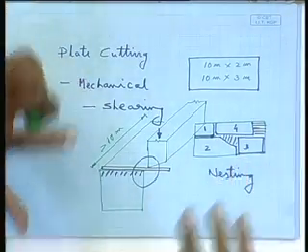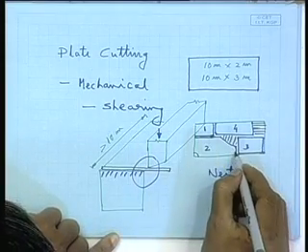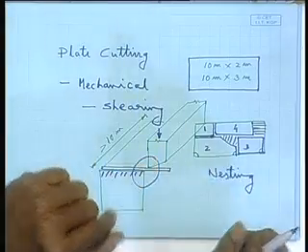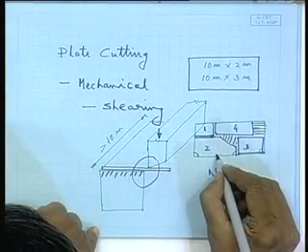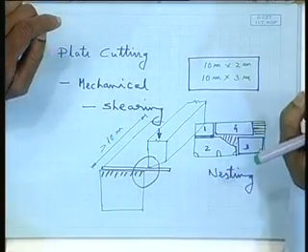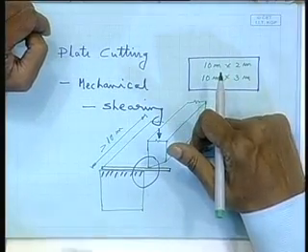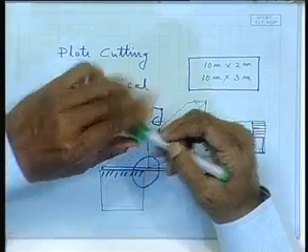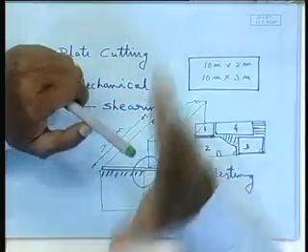Not only that, in many of these cut pieces you will need to have some such thing also cut already in the machine, those scallops, and if there is an angle, all those scallops, the stiffeners are to be fitted, all kinds of scallops, various kinds of curved cut shapes are needed. So, that is not possible here. So, that way this mechanical cutting machine, though very efficient and gives a very good quality cut, with no adverse thermal effects, still its use is limited. Limited to what? Limited to cutting straight edges, because in construction you generally require various rectangular pieces of various dimensions.